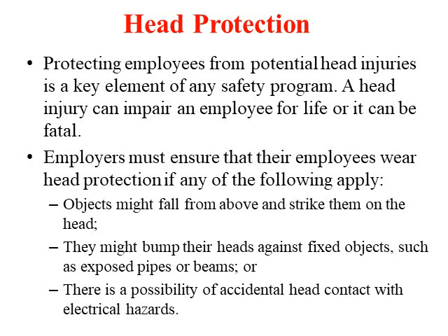The first is objects that may fall from above and strike them on the head. It may so happen that construction work is going on, and if someone walks under it, any object may accidentally fall and hit him. In such conditions, employees are required to wear a hard hat every time. Or there may be places where they may bump their head against fixed objects, such as exposed pipes or beams. Sometimes the pipes may be lying very low, so we need to bend and walk through. During such cases, there are chances that the head may bang against such objects, so we need a hard hat.